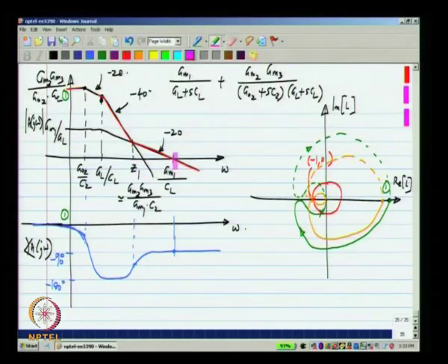In this particular case, we only have 2 poles, this we can analyze explicitly, but in general we can use the phase margin criterion for stability. Now, the way I have drawn this plot, you see that the 0 appears well before the unity gain frequency. So, that means that the phase shift at the unity gain frequency is close to minus 90 degrees. Okay. So, in fact, it is much closer to the green curve than the orange curve.